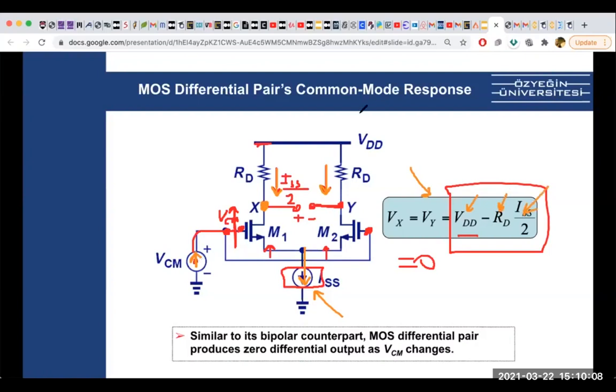So basically, this circuit tells you, hey, regardless of whether you change VCM, as long as this is a strong current source, meaning it has a big resistor, right? As you remember from cascode current mirrors, that's why we were using another transistor to make this Rout bigger, remember? So as long as we use a strong current source with high Rout, this VCM change won't really affect your circuit because it won't change the current on this branch.